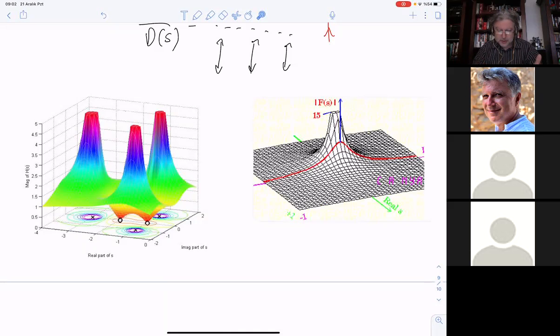We were talking about poles and zeros. The zeros are places where the surface touches the horizontal plane, where the magnitude of X of s or H of s, as you can see here, is exactly equal to 0. But the poles are problematic because they are diverging towards infinity, as you see. At those pole points, the surface is extending to infinity in magnitude.